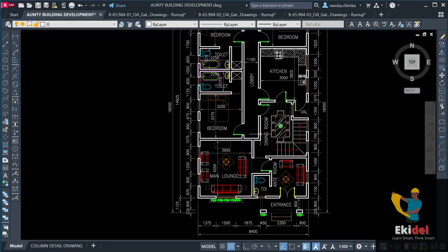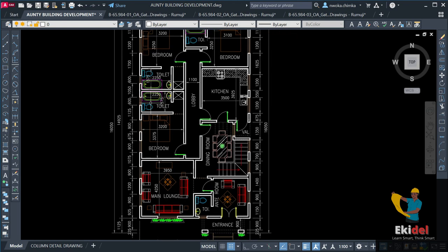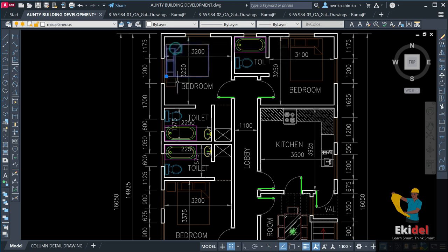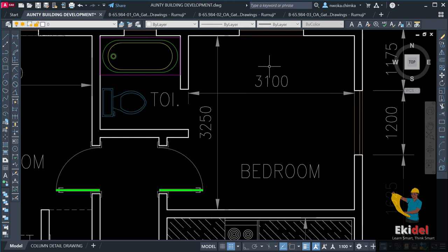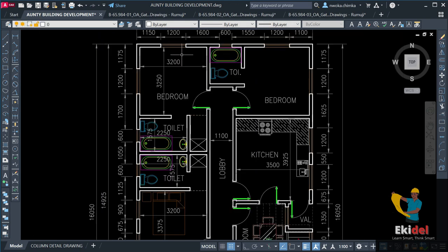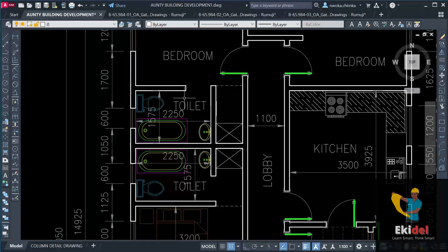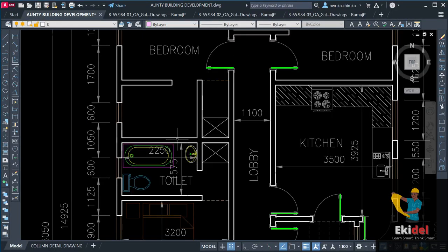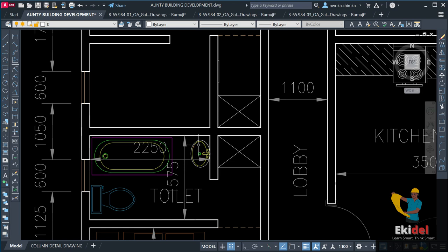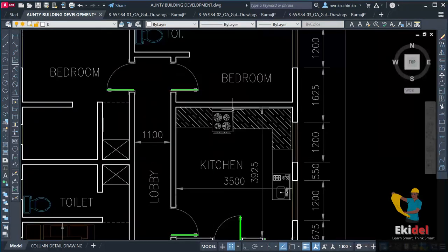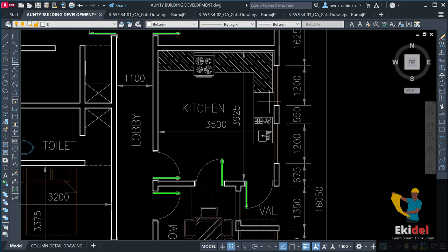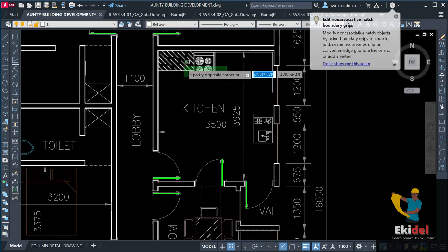Now, once you have copied them out, I always advise, as a structural engineer, that you remove all these unnecessary items which are found on the plan, which are all these bed symbols, because we don't deal with all these symbols. All we deal with is the block walls and other important features. So right now, I'll just remove all these features which are not necessary. Okay, so you can see what I'm doing right now. So you just do that on your own also.